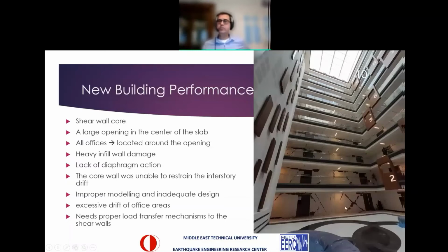There is a shear wall core. Actually, while I am taking this photograph, it was behind me, the core. And as you see, there's a very large opening in the center of the slab, and all offices are located around the opening. Here you see offices everywhere. And we saw very, very heavy infill wall, non-structural wall damage in this building. And it is a new building.